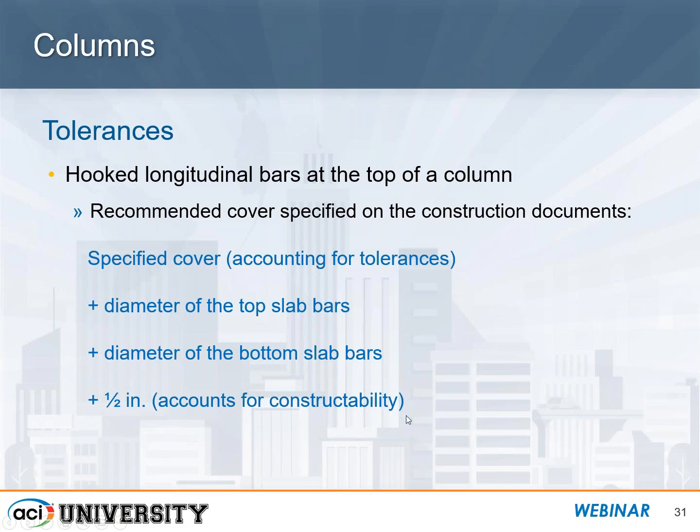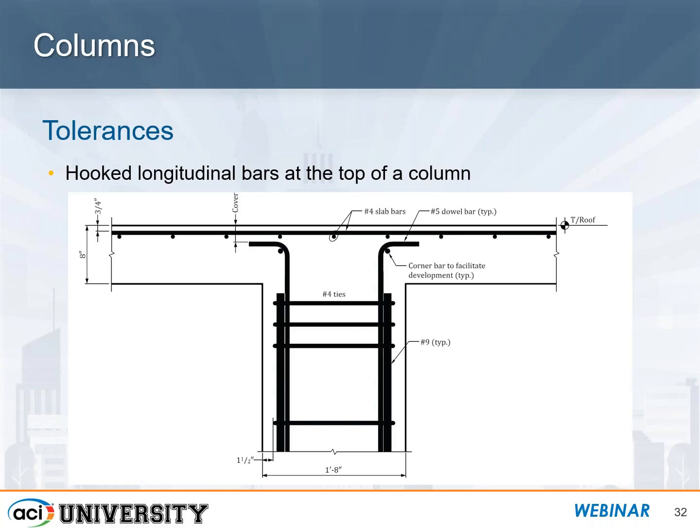And if you provide at least this cover on your drawings, on your typical drawing, on your sheet for column schedule, you're going to alleviate a lot of possible constructability issues in the field. And this is the other thing we recommend. So here's that cover that we have outlined on the previous slide.